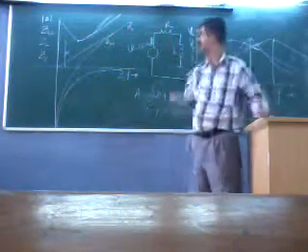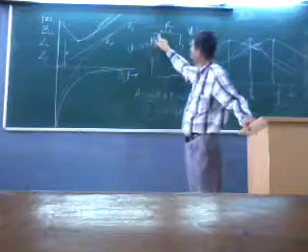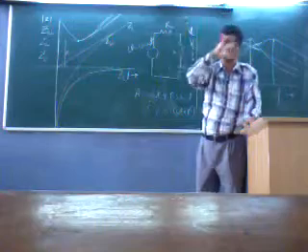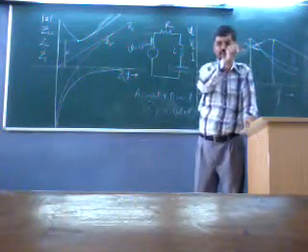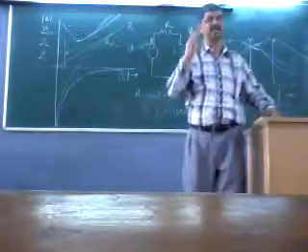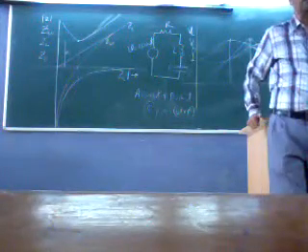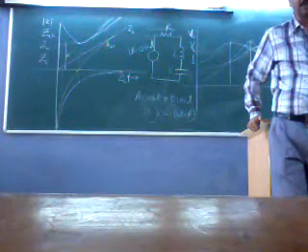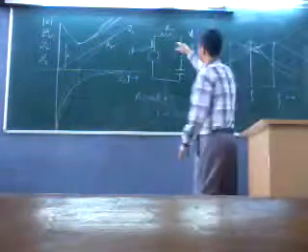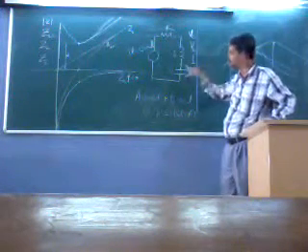I would like to again clarify. Here, amplitude is 1, V equal to cos omega t. So there would be some voltage across the resistor. It is a sinusoidal function, something cos omega t plus something, or a cos omega t plus b sin omega t. There will be some voltage across the inductor and some across the capacitor. Each of them has some amplitude and some phase. Those would be functions of frequency, all functions of omega. And as all are functions of omega, when I is peaking, the voltage across the resistor is peaking at that time. There will be some frequency at which VC has its maximum value.